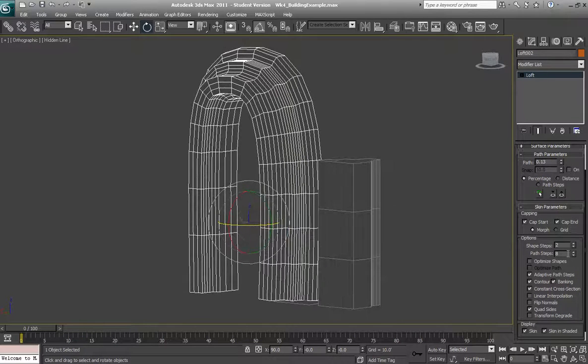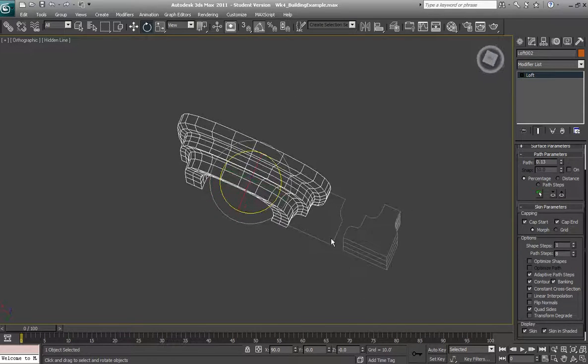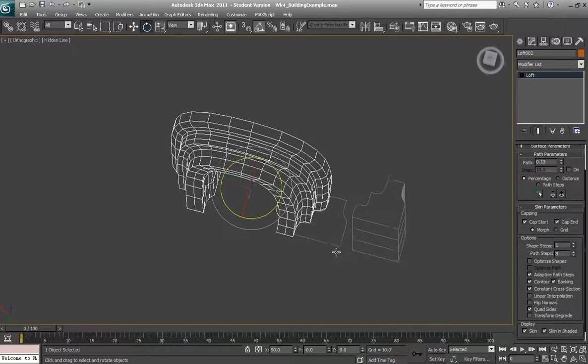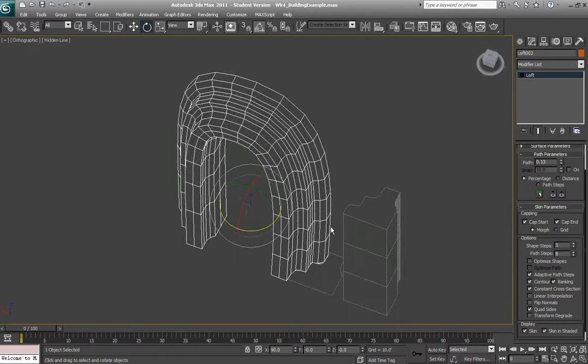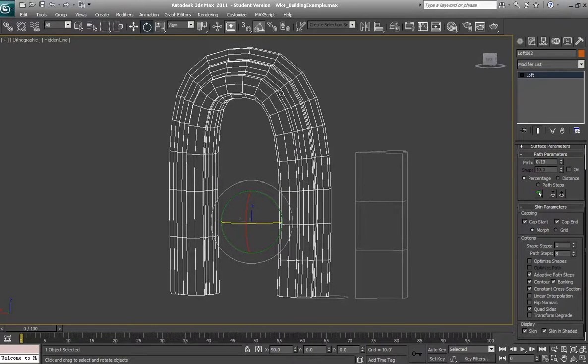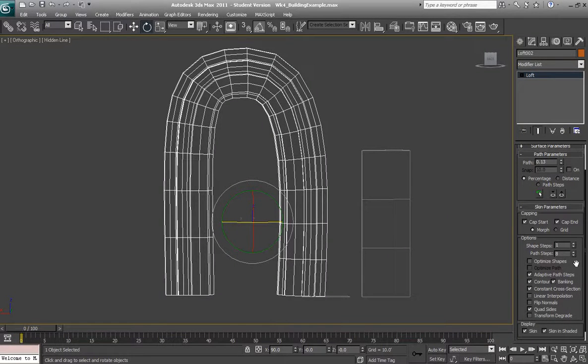The suggestion that I would make is to go light on the number of knots that you set out for your shape, and if you have an archway, allow yourself to put more polygons in the arch so that it does not look so angular at the top.